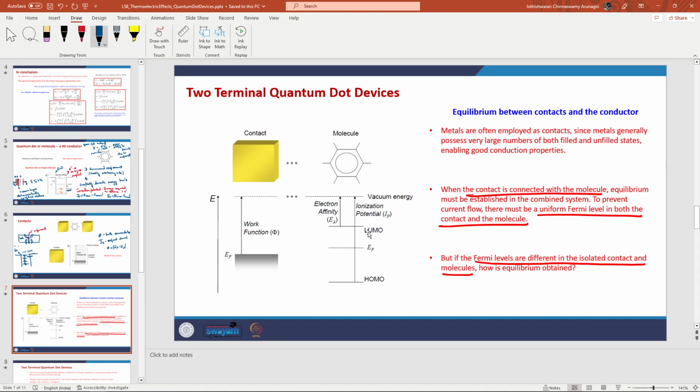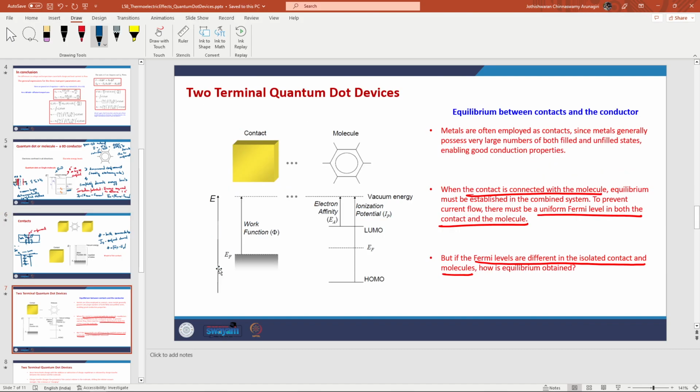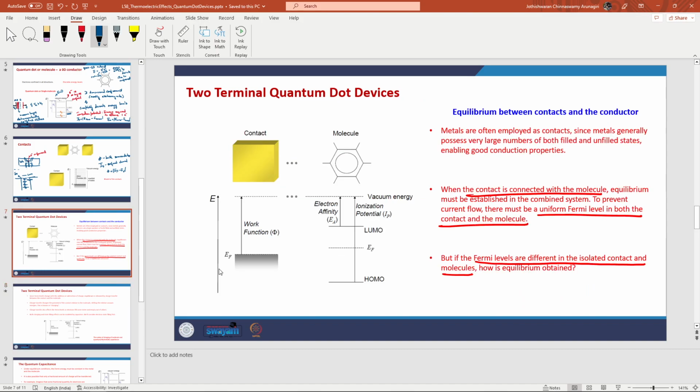Of course, now there is an important question. Here we assume that the source and the drain are of the same material. Now, what if these were not of the same material? What if they were, kind of, above and below? In that case, how will equilibrium be achieved? Essentially, instead of using a metal, let us say I'm using a highly doped semiconductor, which can also provide as many free electrons. So that equilibrium configuration cannot be obtained in a straightforward manner,